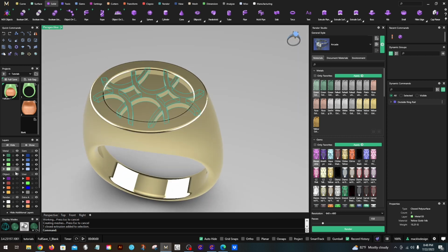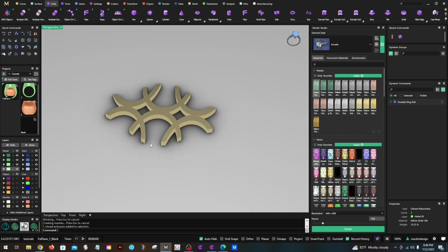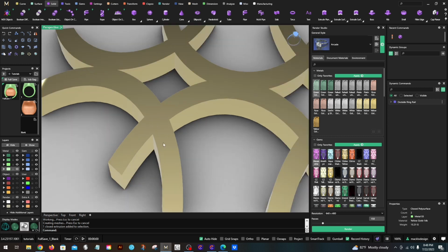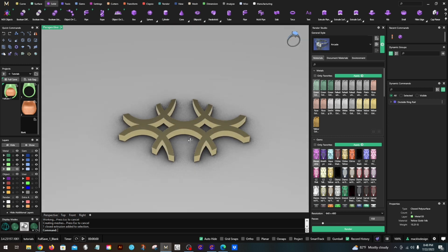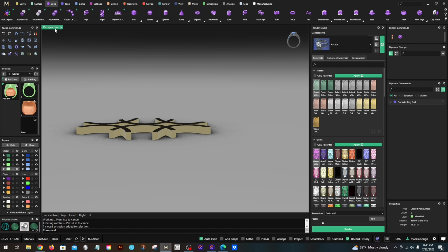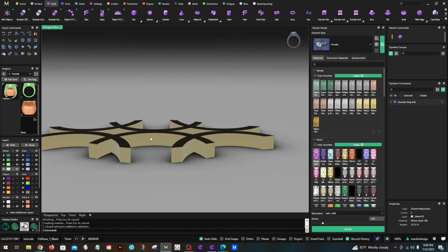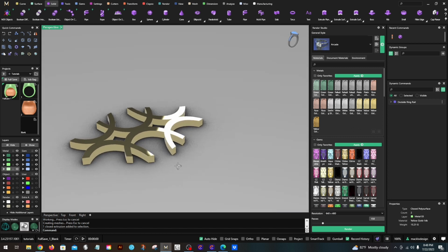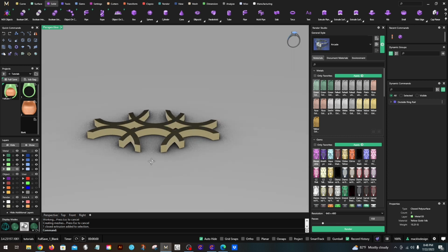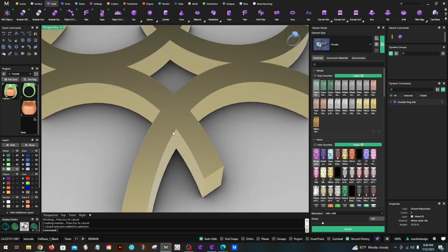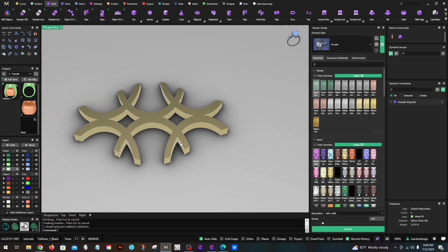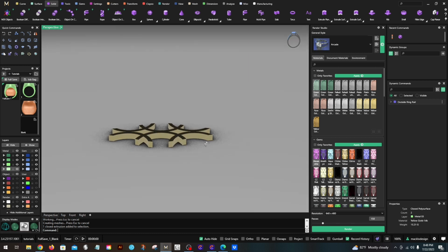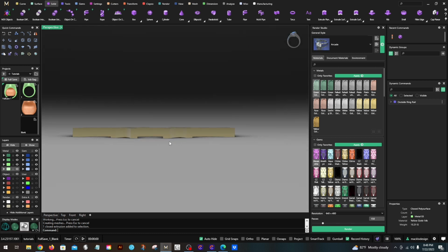And now if I want to fillet this, I will usually hide everything else because this is going to be a little bit tricky. It may or may not like what I do. So in filleting, the top only, right? Now you could fillet these edges too, but I think I'm just going to do the top to keep that sharp. You don't want to fillet the bottom because it's too close to the bottom of the cutout.